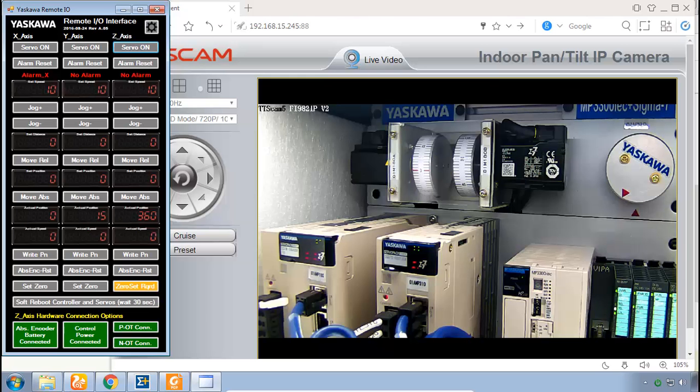So I've got remote connection to the demo system here, and I think the easiest way for this controller to give a command that produces an alarm in the servo is to set the speed too high. Let's turn the servo on, and then set the speed to 4,500. Now if I jog at that speed, you see the motor took off, and I've got now alarm AD00. That's even displayed for me on the HMI. But what does this code mean, AD00?